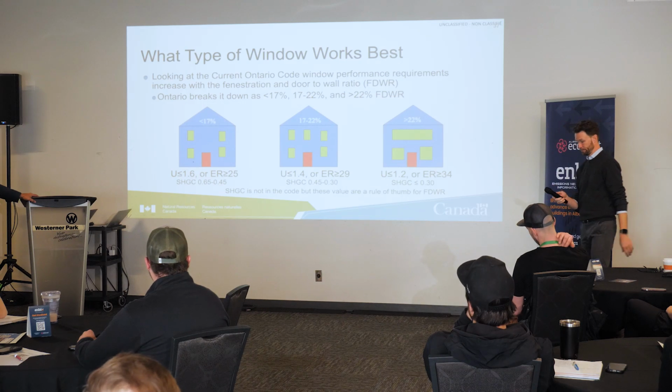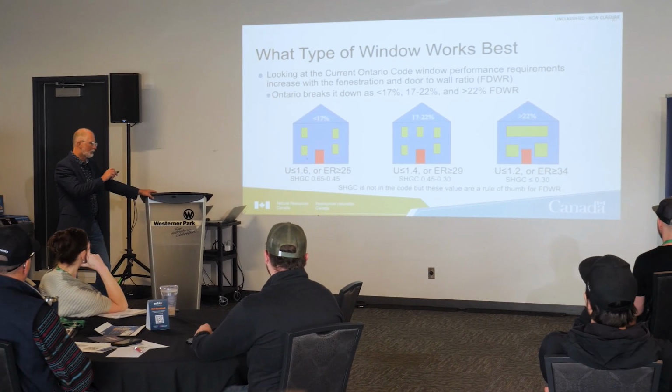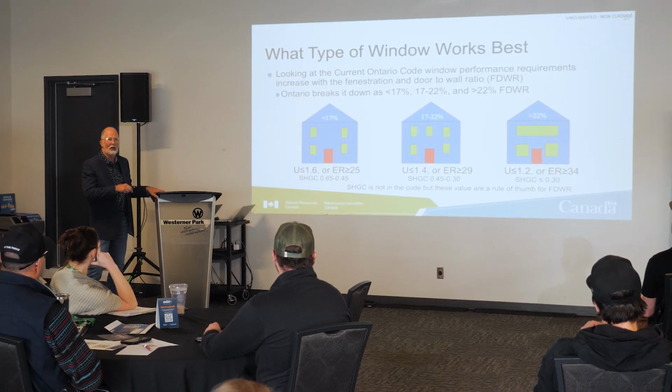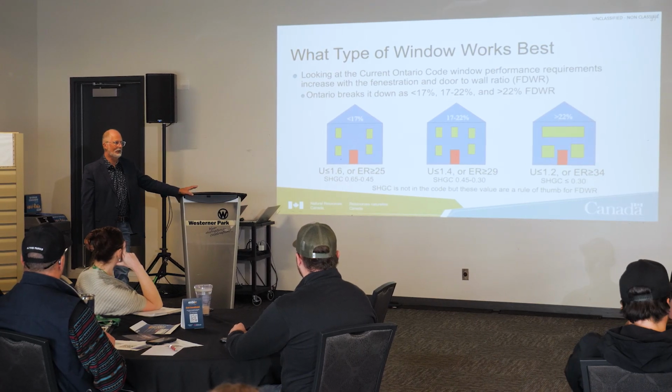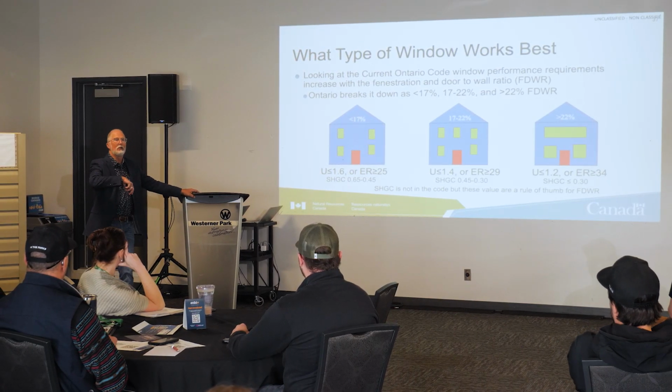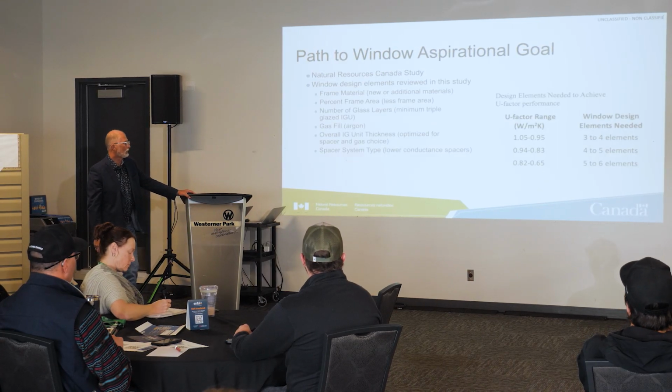Yeah, exactly. And I know when we did the first code, we could cheat the system. We could run everything at, you know, 0.65 and they performed beautifully, but we were overheating those houses ridiculously. So now we've got the peak cooling loads that have come in, and in the next code cycle, we'll go even further.